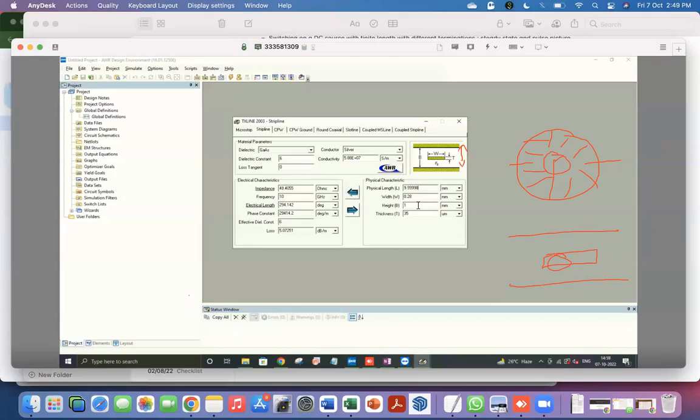So as a designer of a microwave transmission line, you have some constraints, that you have some material to choose from, and then the only design parameter you need is the width of the center line. So if I put this to 50 ohms and do the calculation in reverse, it's not going to touch the height or the thickness of the center film, because that is decided by the choice of the board.